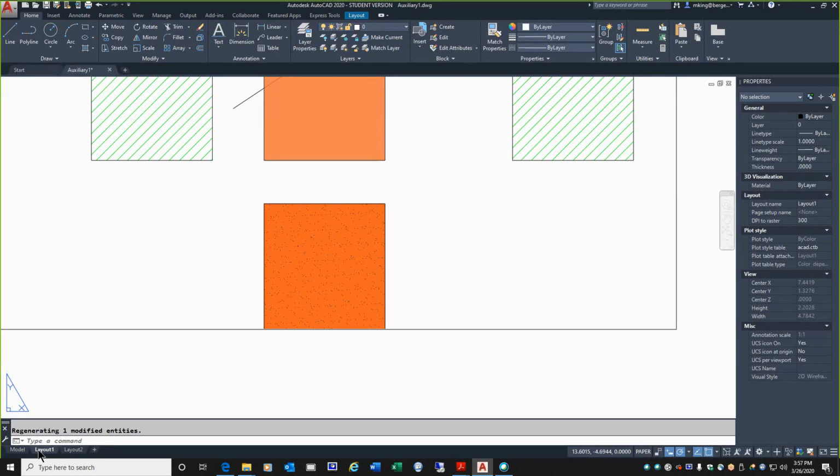Now, you have to be careful because as you draw and edit, it is possible for AutoCAD to occasionally get confused, and all of a sudden the texture is gone. Like, what happened? I must have accidentally erased it. And you do all of this over again, continue working, and you look back and it's gone again. What's happening, I can almost guarantee, is that the draw order gets reversed, so the sandy pattern goes behind the solid pattern.